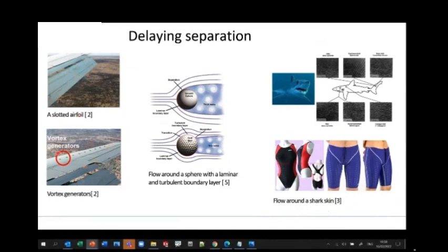Other examples that we might see are these vortex generators. So here's another aerospace example where we're using that geometry there to introduce some turbulence, to introduce some kinetic energy within the boundary layer, and by introducing that kinetic energy, again we're delaying the separation on that object.